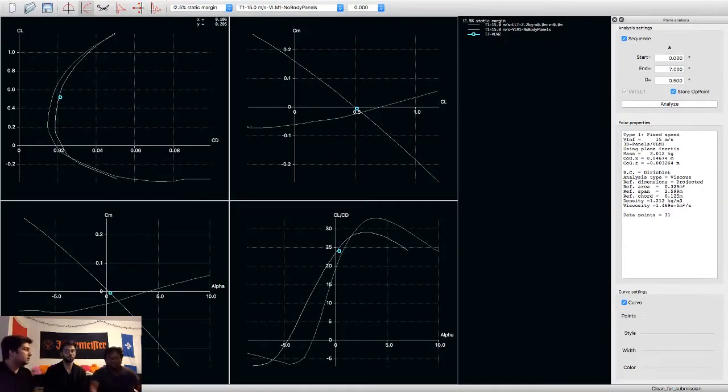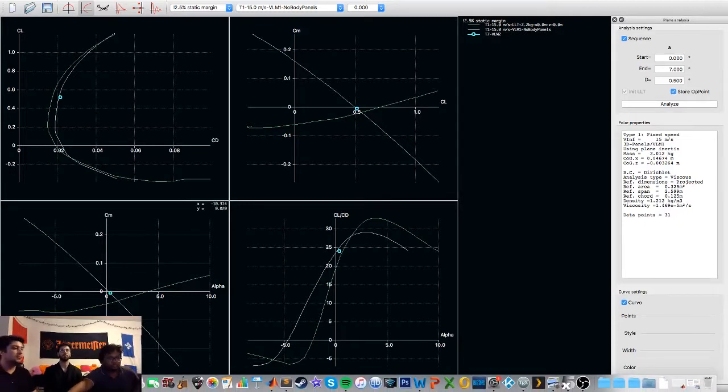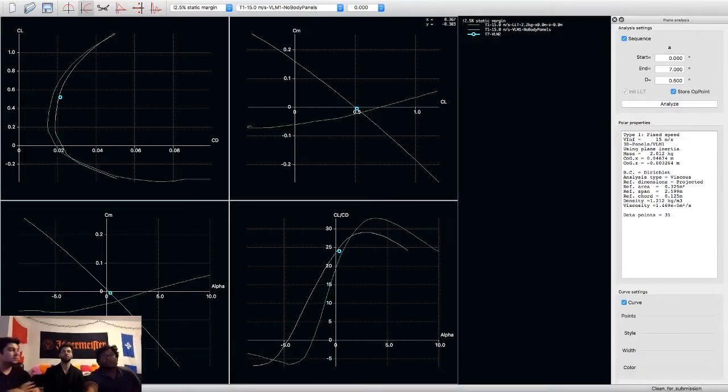Yeah. So for the stability analysis, we estimate the neutral point by changing the position of the center of mass, and by changing the position of mass, we got the slope to be 0. That point is the neutral point, and after finding the neutral point, we calculated the static margin. Using that, we got a 44% static margin, which is good for our longitudinal stability.